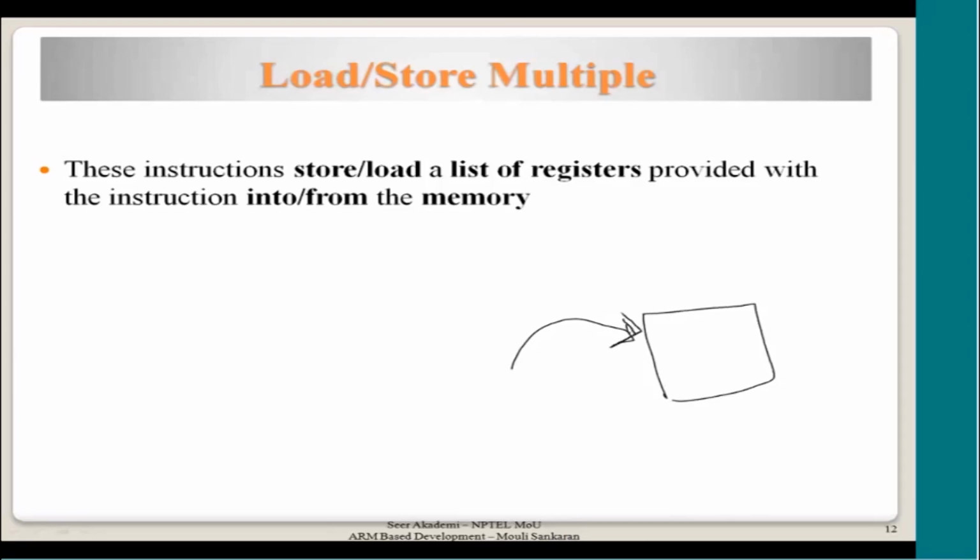The control flow is totally changing from the normal flow. Now inside the exception you will be using the registers which you were using in the normal flow. Okay, a set of registers. Before the exception or ISR, interrupt service routine, uses those registers for its own purposes, you should save the set of registers into the stack.